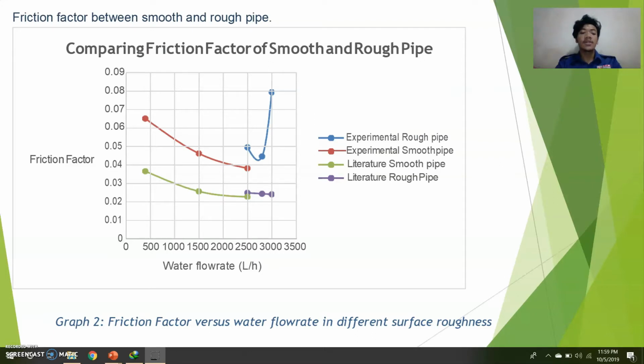In addition, turbulent flow can also form a thin viscous sublayer near the pipe wall, which can be a function of roughness. Generally, for a pipe with a large wall roughness value, the effect of roughness is even larger. Consequently, a pipe with higher surface roughness will have a higher friction factor. However, the viscous sublayer for a smooth surface pipe is extremely small and negligible. Therefore, the friction factor for the smooth surface pipe is relatively small.